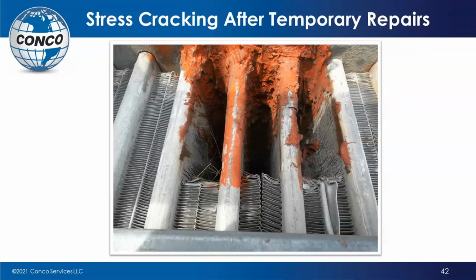We find a leak, the plant goes in and repairs it. Not commenting, the repair's fine. They cut away the fins and use some material to seal that up so that they don't have that problem. But if you look at the one tube, right at the end of the red material, you'll see that the tube is cracked. What has happened here is you have moved the stress from the end of the unit, where it's butting up against the weld points, up to where the tubing itself is.